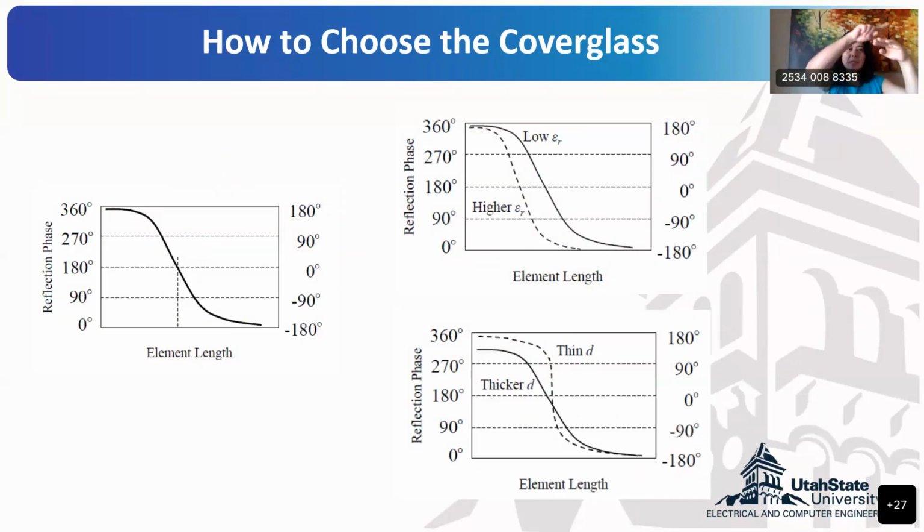So with those design equations, we design the phase response. Oftentimes that's how the phase response looks. You draw the phase response, and that line down gives us the size of the element. That's how we determine at each location the size of our reflectarray element. And that element can be a patch or some other geometry that I will talk about. With that phase response curve, it also allows us to choose a substrate thickness as well as the dielectric constant of the substrate.